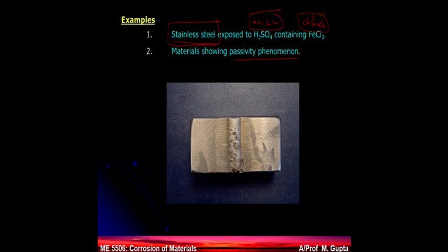Now let's try to understand this point number 2. You have a stainless steel pipe, for example a long pipe, and it is covered by chromium oxide, so it is giving the protection. But for various reasons you put in a solution unknowingly, acidic chloride. It says stainless steel is stainless, doesn't matter, but this chlorine damages the passive layer, so now you have a small pit formed here.